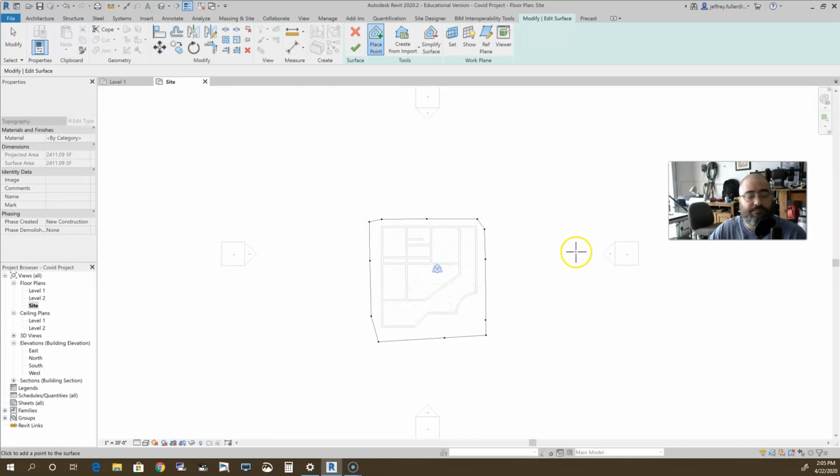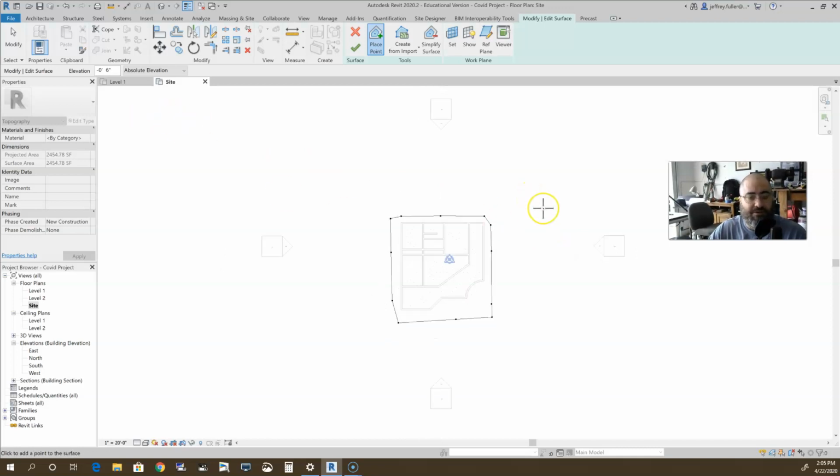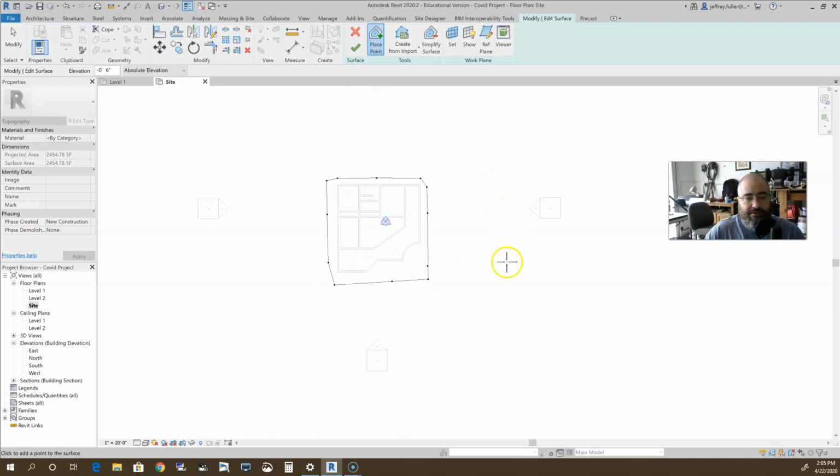There's one more right there. Okay, so that's for right up next to my structure. Then as I move out from my structure, I can increase that elevation, make it higher. Of course, some other things will come into play, is that I would want to have this shaped to where the water can drain in a certain direction, so it can drain however the civil engineers have that set